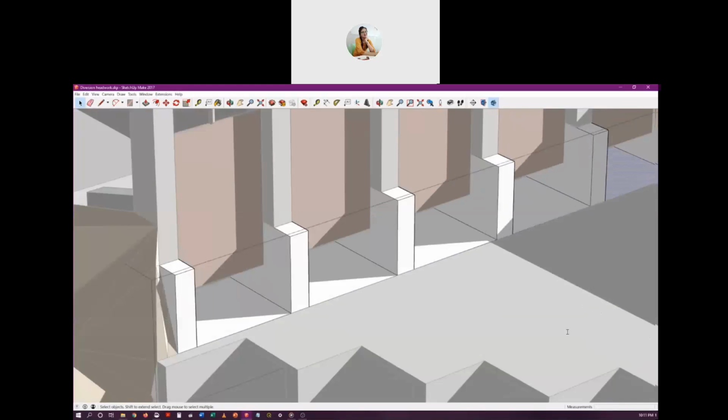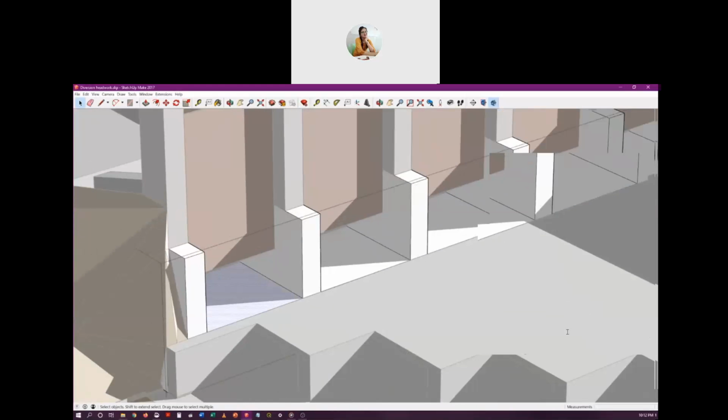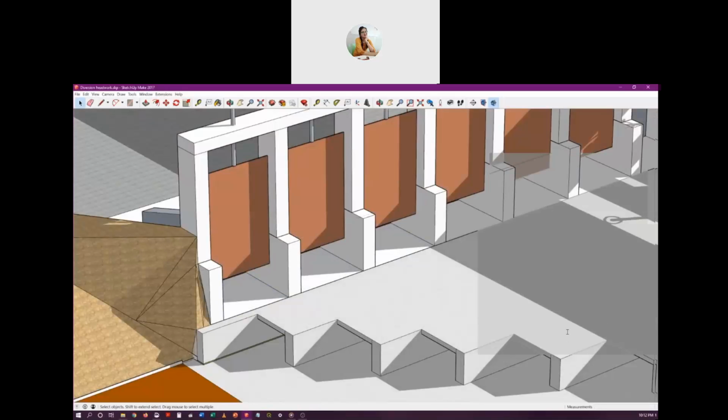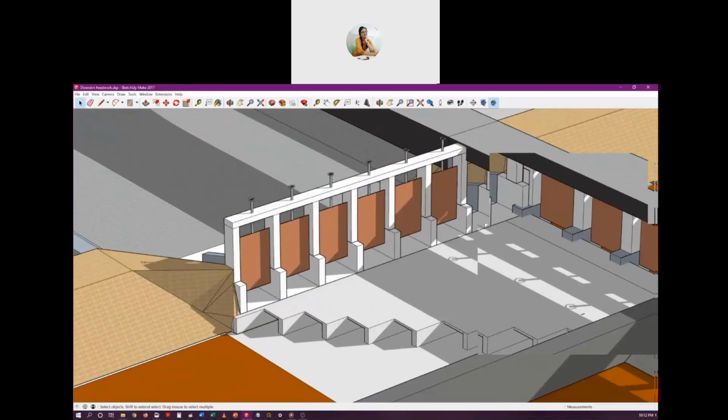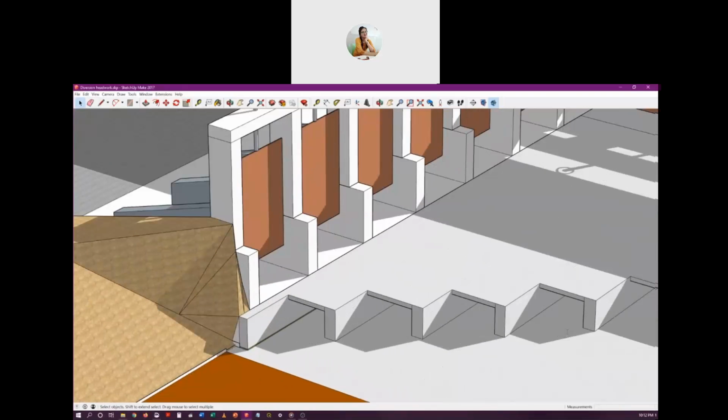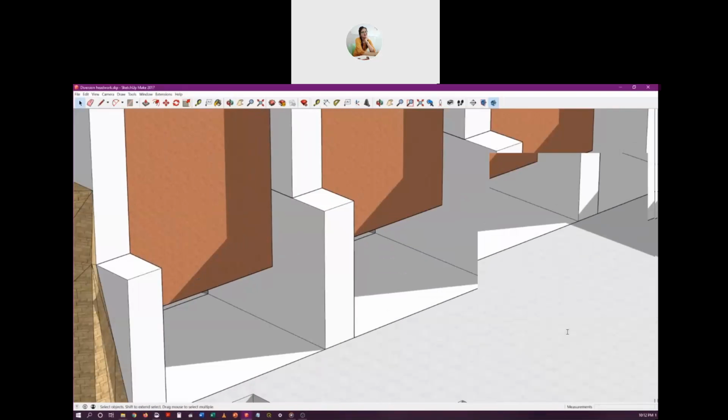If the riverbed itself is much lower, suppose 2 or 3 meters lower than this level, then these kind of silt excluders are not needed because the lower part is already much lower than the sill level. So therefore, the sediment which is carried by the lower portion of the current will not be able to enter these gateways.